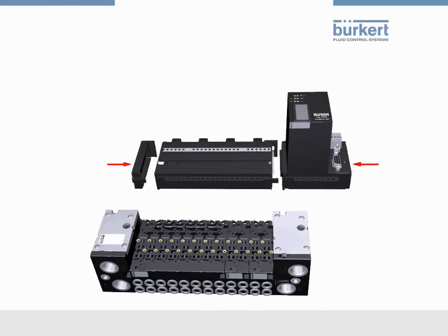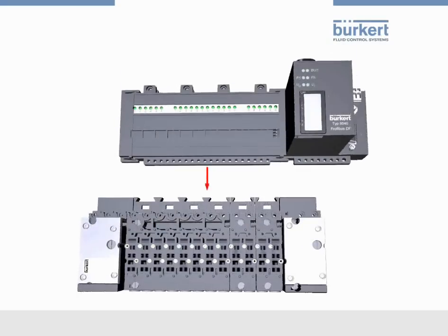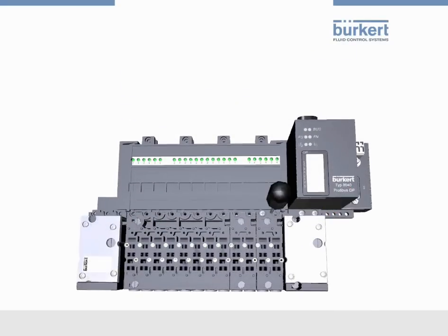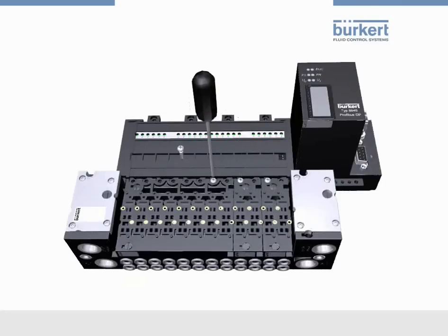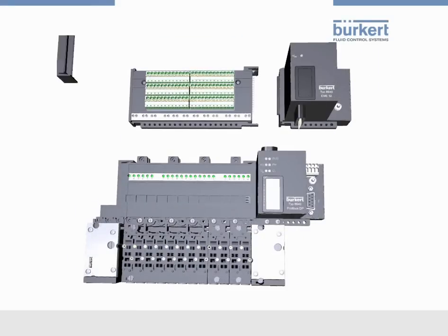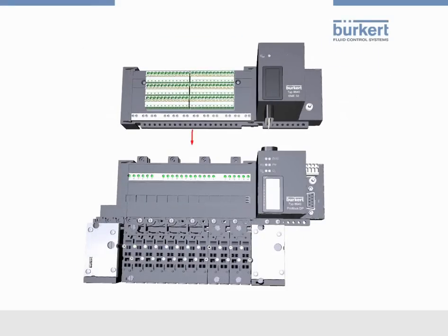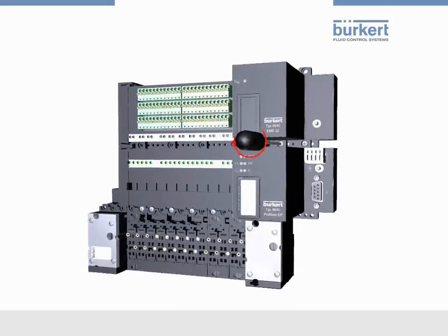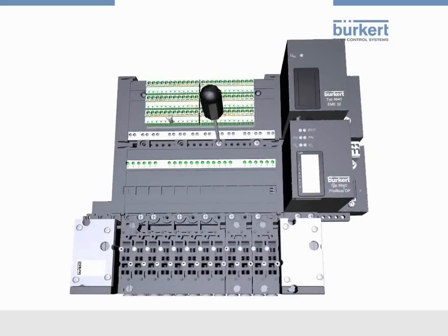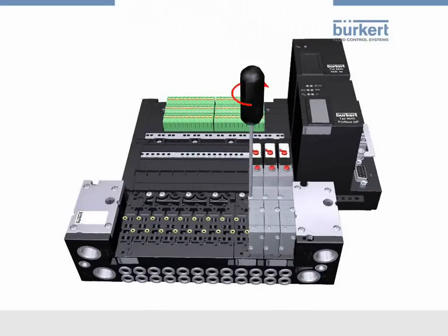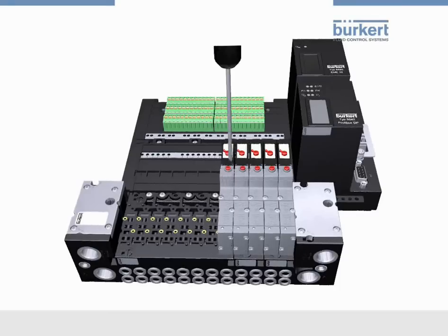In the next step, the communication module, as well as the electrical basic module for the electrical power supply, are mounted. The electrical connection technology allows a Fieldbus interface, common connection, or multi-pin interface. In the new layer, you can add digital feedback inputs. A valve island uses these digital feedback inputs, for example for the processing of sensor signals, and uses the pneumatic outputs for the control of single and double-acting actuators. During the last step, the valves are mounted on the pneumatic basic modules.